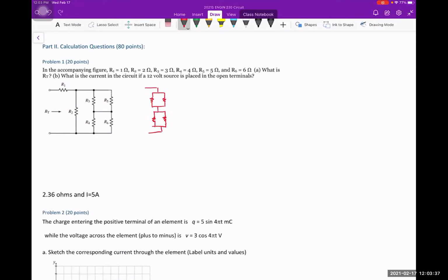So that is the same way as you have on the right-hand side. The 3 to 6 actually connect in this way. So if that is the case, then you can write a shorthand notation for this part here, which is simply R3 parallel with R5, and they're in series with another 2 in parallel, which is R4 parallel with R6. And then you connect this one to the R2, where the whole thing is parallel to the R2.